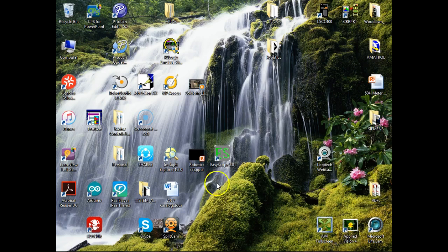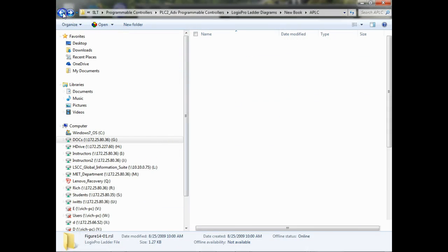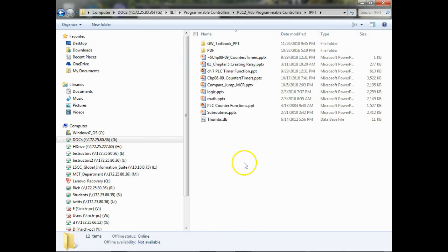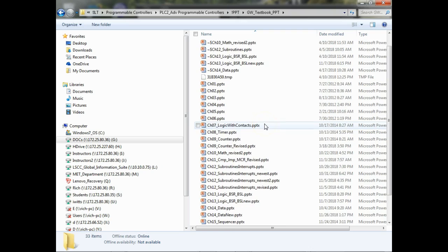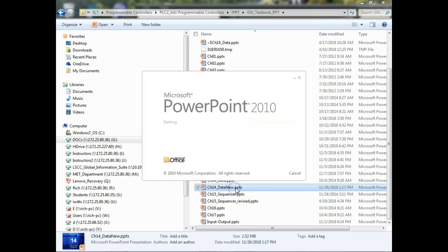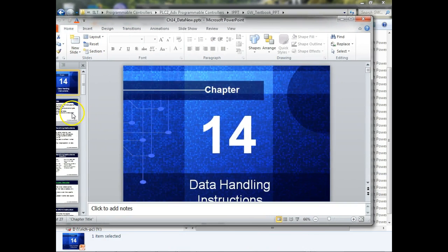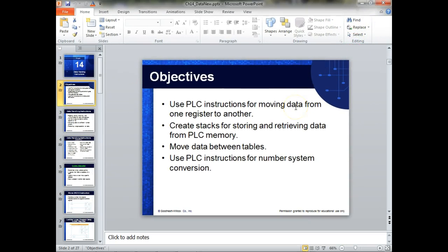But I just want to drop back and read these. So what did we go over? We were talking about the last part, the data. Okay, so any questions on the move instruction? Just move. Any questions on the move instruction? Pretty straightforward, right? Everybody okay with move with mask? It's an and mask, and what do we use and mask for? To make sure certain bits are cleared, right? So we strip off what we don't want.